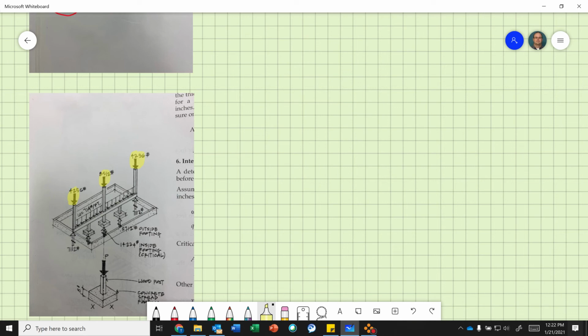You have to remember these column loads actually transfer through and go right onto the top of the foundation wall. So this is typically where you'll see a pilaster in your foundation wall, that bump out that creates kind of a mini column.